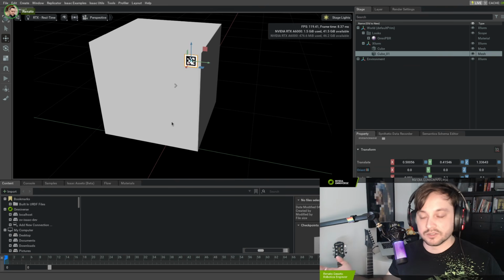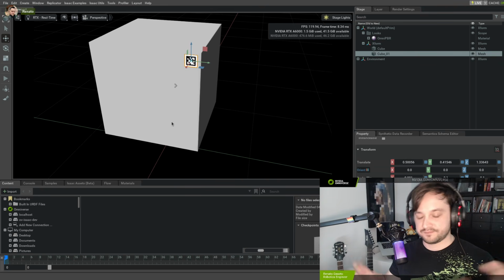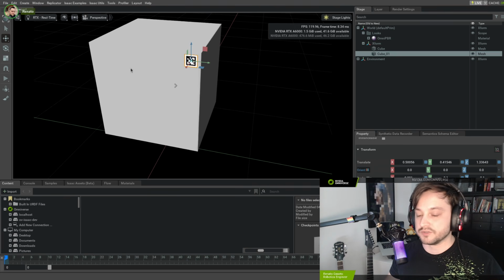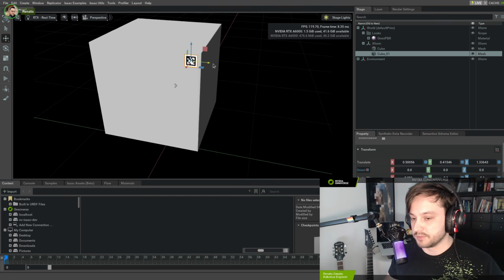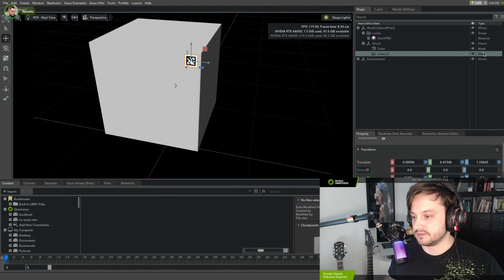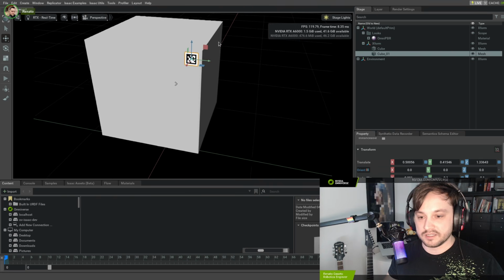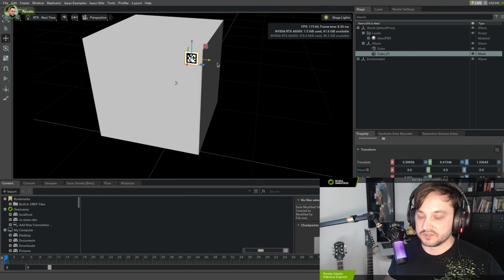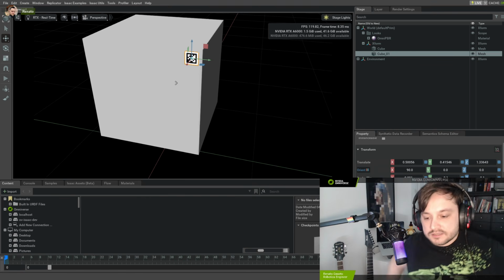Alternatively, you would have to go on Blender, set up UV maps, and then downscale your April tag to that specific point. But I think this is an easy way of putting an April tag where you want without too much effort. Just get a single mesh that has a cube there, apply the April tag, and put it here. And if for some reason this is rotated, which shouldn't matter for an April tag, but if you need, you just come in and rotate it however. Okay, cool.